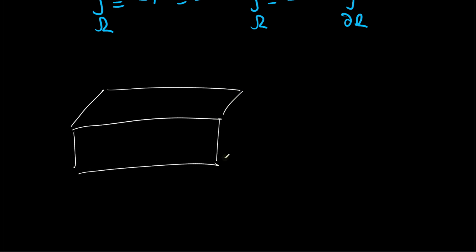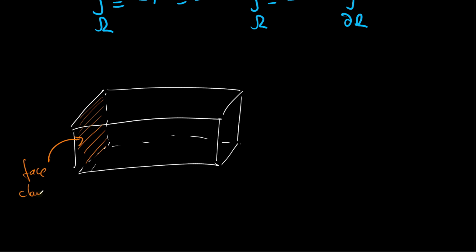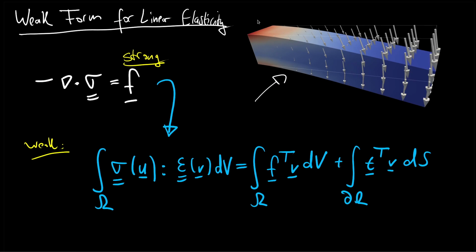So this was a three-dimensional problem, so we were looking at this three-dimensional domain here. And the idea of the beam was that the entire left face is clamped, so this face is clamped, and clamped means that our primary unknown, the displacement vector, will be 0. So our cantilever beam is not allowed to displace on this left face.